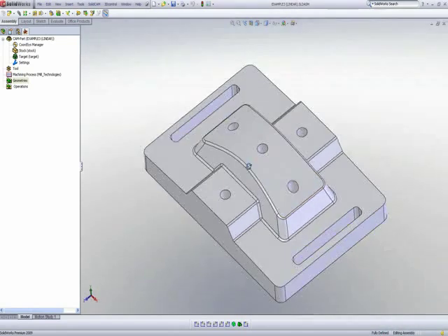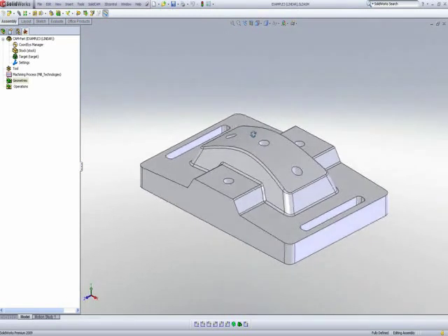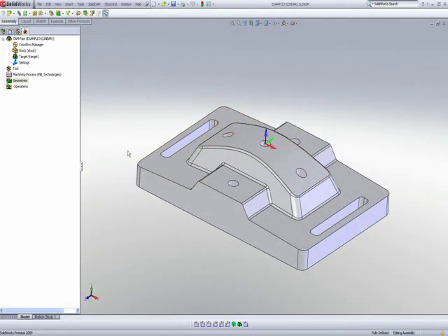If we take a look at this particular part here, I'd like to use a finish cut of linear machining, going across back and forth on the part itself, and I'd also like it to skip over these holes and the slot area as smoothly as possible. At the end, I'd also like to finish off these corners using what we call rest machining.